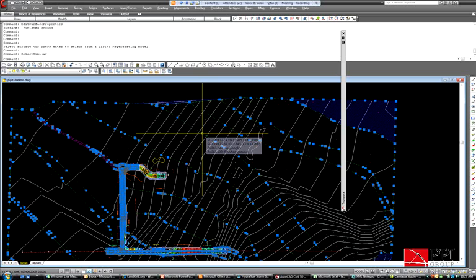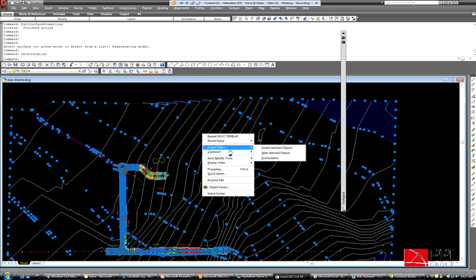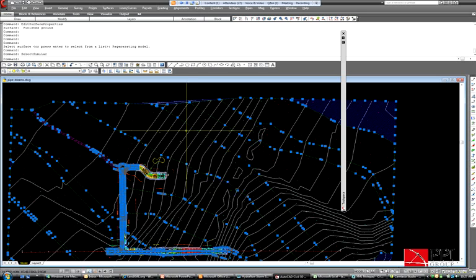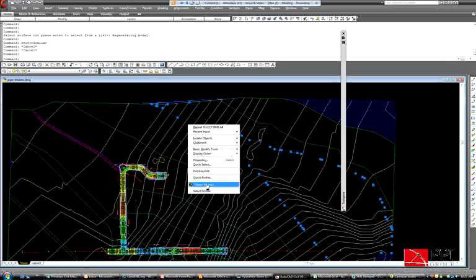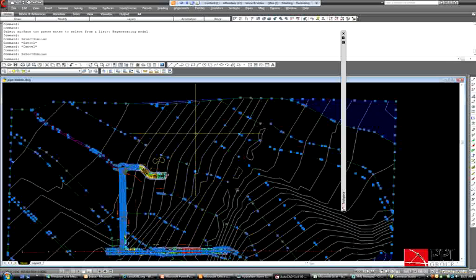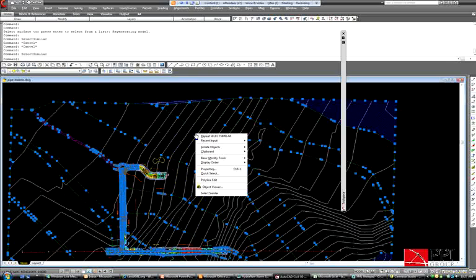And what I want to do here is first use isolate objects. These are tools that are extremely useful and relatively new to the program. Not everybody's aware of them or using them. So just to go through that one more time: right click, select similar, right click again anywhere in the screen, and you can isolate those selected objects.